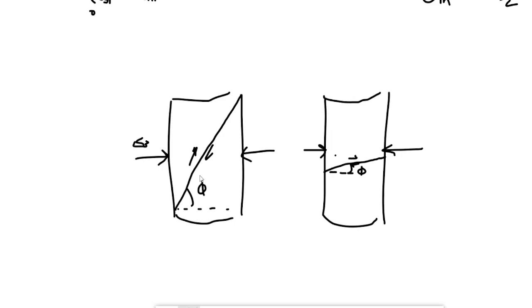It would be like, maybe your car would be a better example. If you load that thing up, all of a sudden the load is perpendicular to the plane. If you're worried about sliding around on slippery conditions, you maybe put some weight in the trunk or the bed of your truck, and it helps you out. Same sort of deal. The more perpendicular you're acting to that sliding surface with your confining stress, the more efficient you're going to be at increasing that resistance to failure along that plane. That's the really important point.